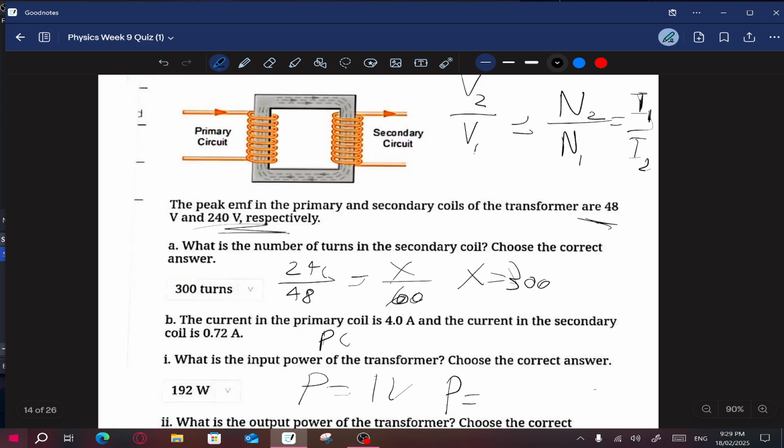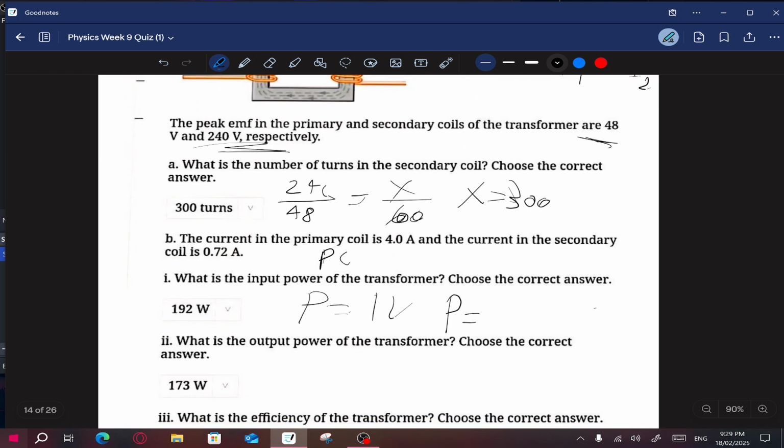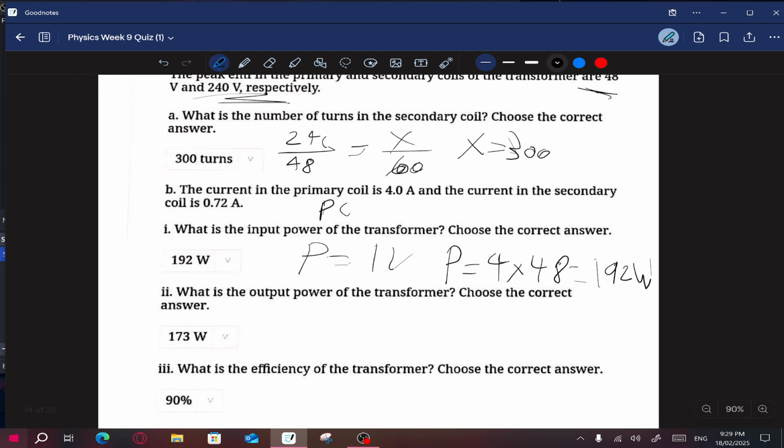Okay, just take the power of the primary, which is 19.8. And the secondary power is P2. This is milliamperes, so this is 162 times 10 to the power of negative 3 amperes, times 110 volts, which gives me 17.82.